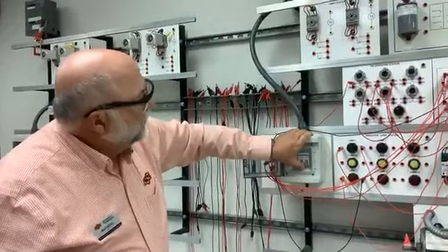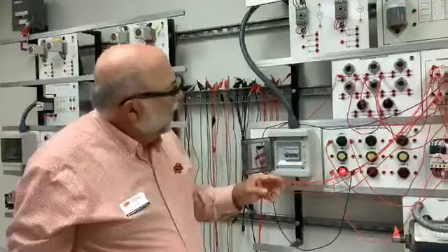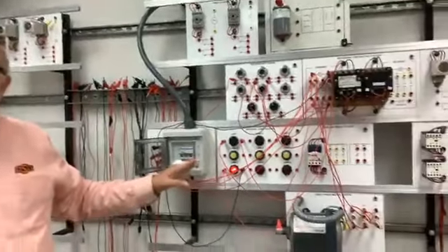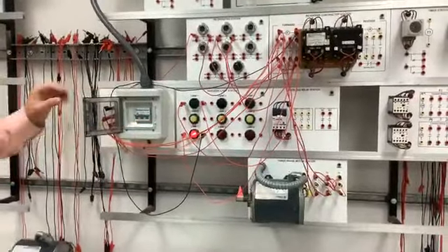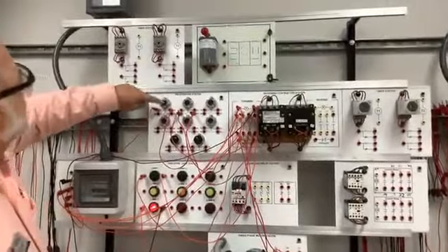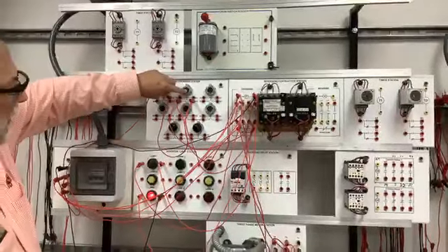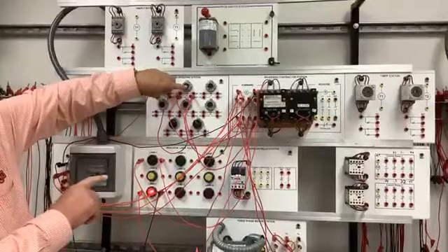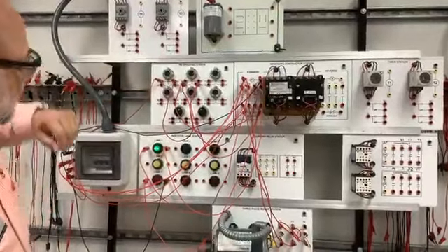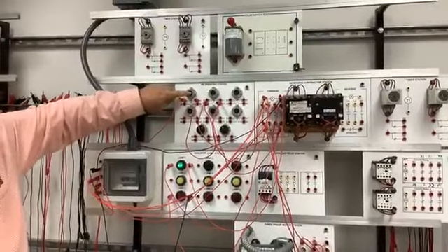Whenever I turn this on, the way the circuit operates up on the board here is when the motor is off, a red light will come on, so it's going to stop. And whenever I press the start button, we'll see here, here's the stop button, and then here's the start. And we'll see that the green run light will come on, and then the motor will energize. There you go. The simple start-stop circuit.